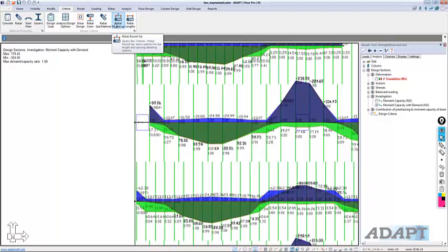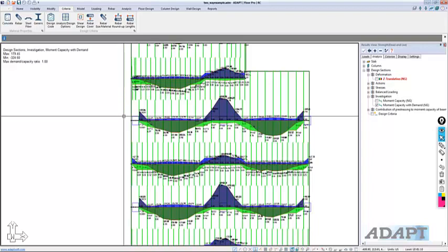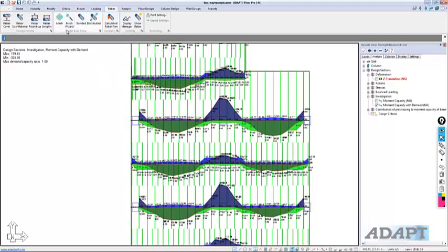You can also make settings for rebar roundup and rebar lengths, and that's more for just output and detailing of the reinforcement. If you wanted a user-defined rebar and add, for example, a mat of steel or isolated bars, you could go to rebar and model reinforcement in the slab, which would then be accounted for in the design.